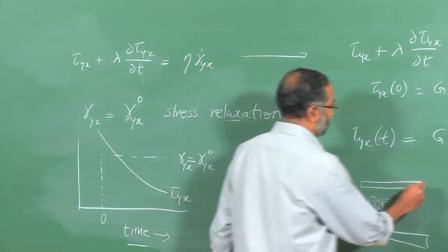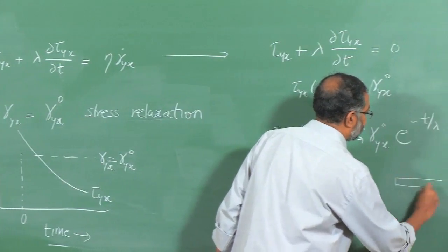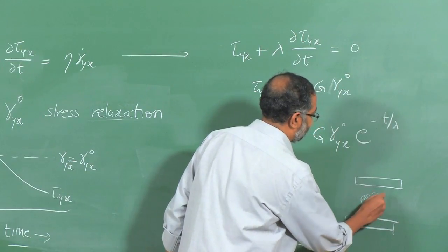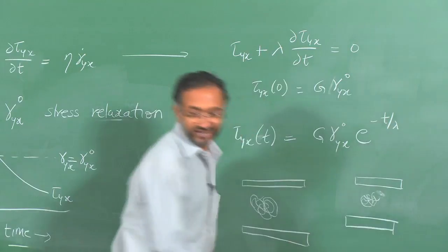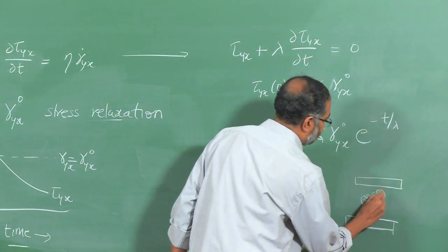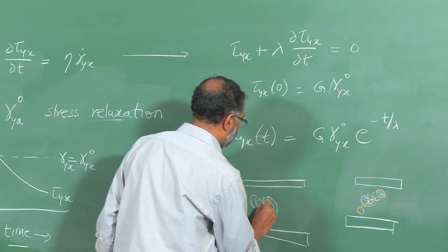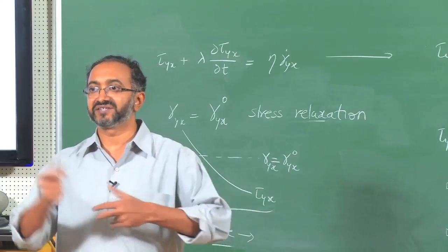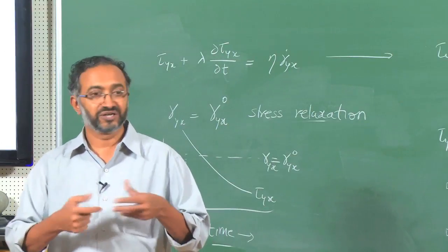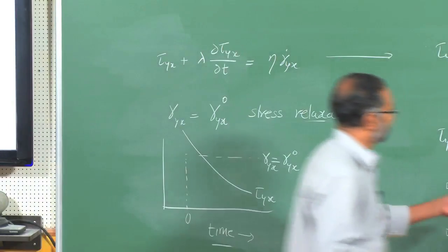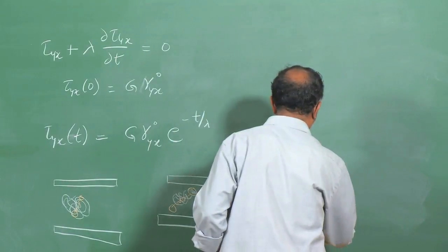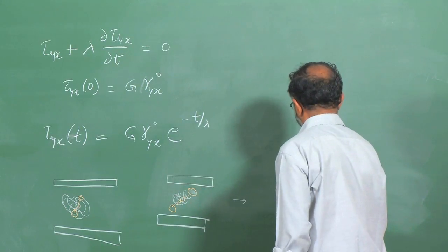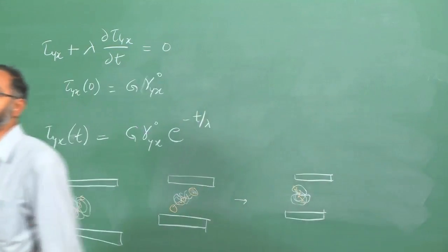So, if I apply a small deformation, this molecule will get extended instantaneously, right. So, the spring and dashpot that we had visualized earlier will be longer, so it suddenly got stretched. But over time, since there are fluctuations present in the material and segmental flexibility is there, this particular molecule in the new, deformed state will again occupy the same spherical conformation. Which means it will come back to the same length. Of course, its orientation may also continuously keep on fluctuating.